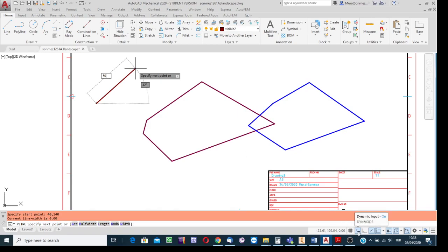But if it were off, then to be able to teach the software that the number written for the second terminal point is with respect to not the absolute origin, but with respect to the first point preceding the located point, and it is not x but delta x value, I would bring the at symbol first.